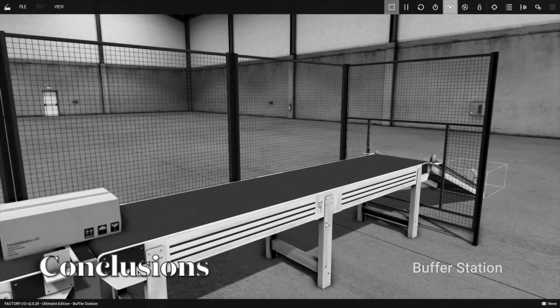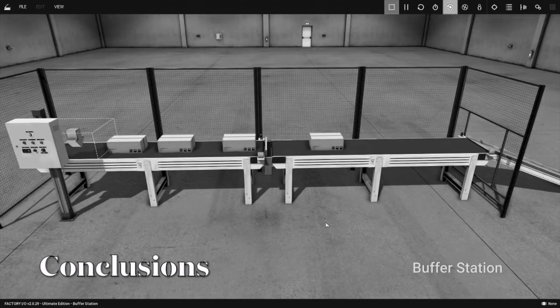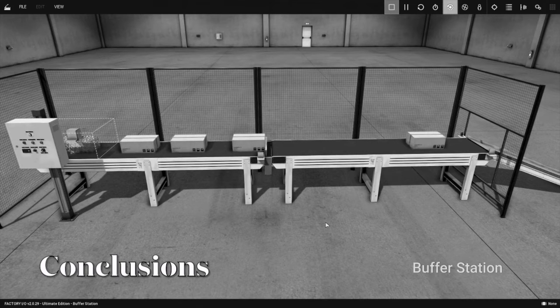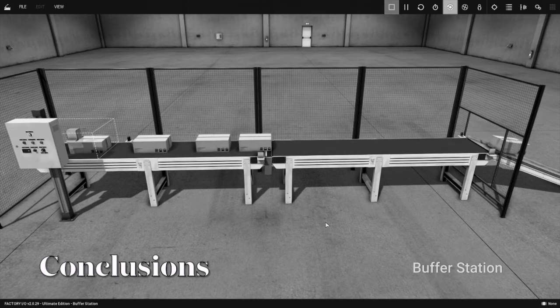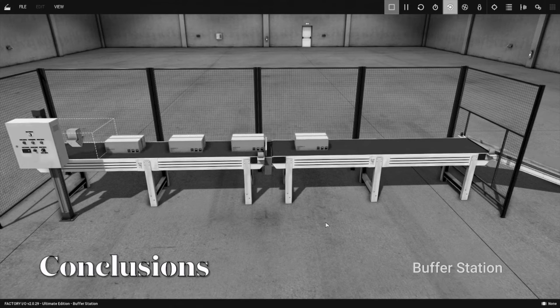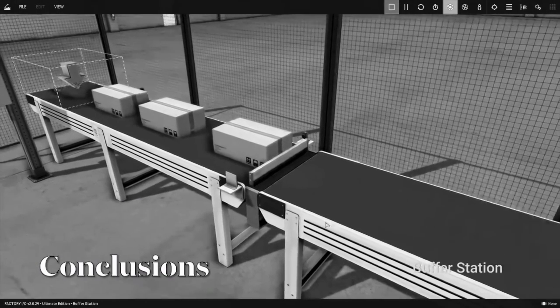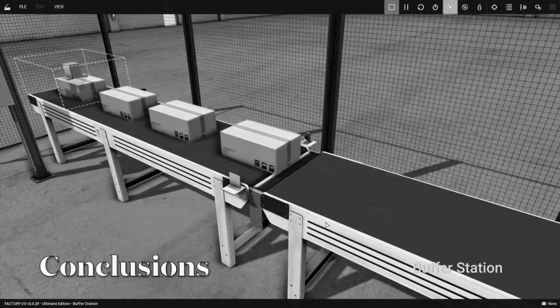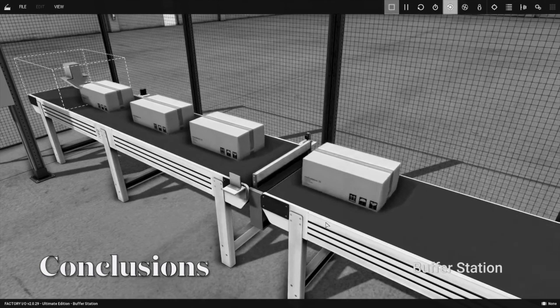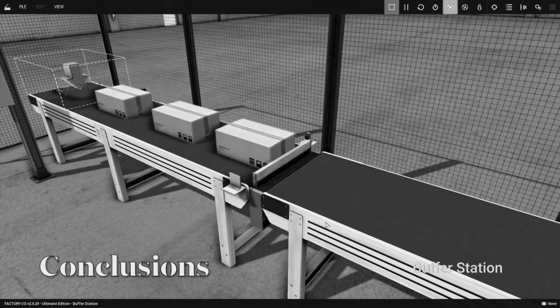In this first challenge, we integrate several concepts learned in class, such as connection and configuration of a PLC and its components, connection to a digital twin through OPC communication, handling of ladder programming such as open and closed contacts, interlocking circuits, coils, counters, among others. And we managed to integrate everything in a small project to demonstrate its operation.